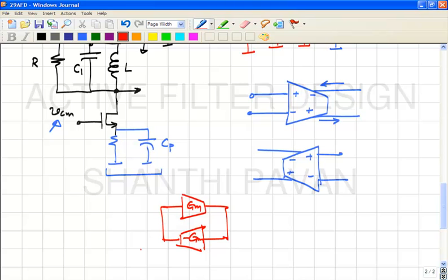All I'm asking is to help me figure out how I'll arrange this. Now I have a differential input, voltage controlled current source, two of them. In the single-ended schematic, the output of the first transconductor is being sensed by the input of the second transconductor. So, in the fully differential schematic, the differential voltage at the output of the first transconductor must be sensed by the differential input of the second transconductor.